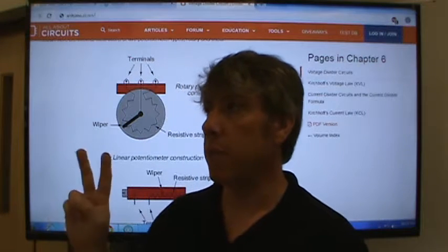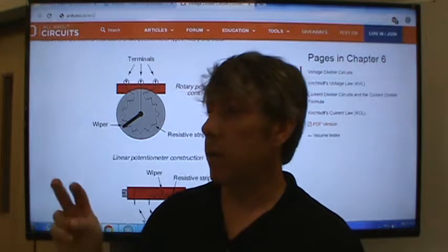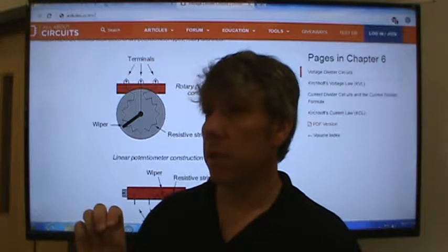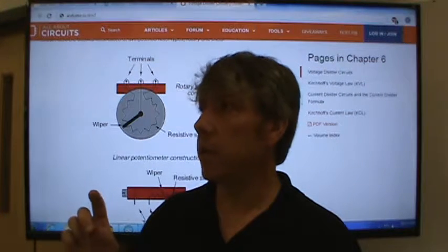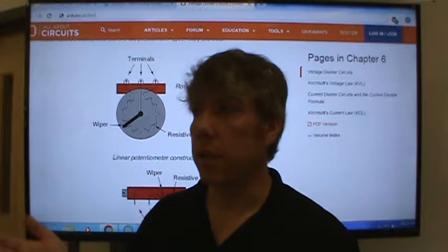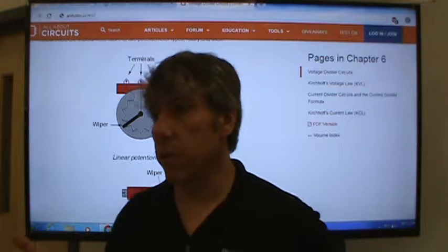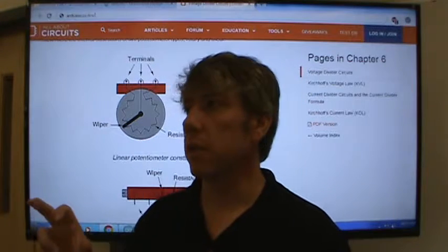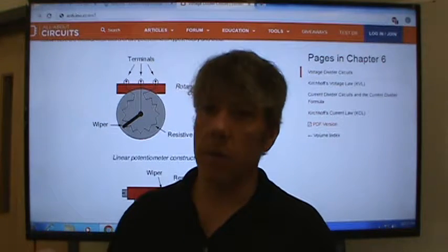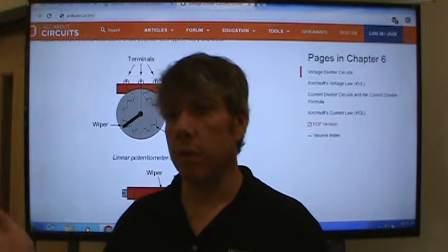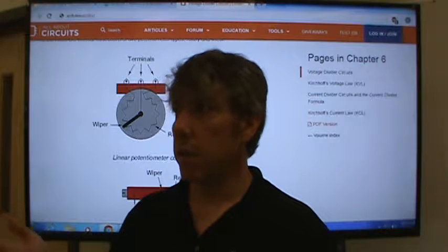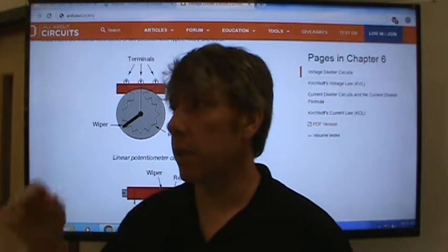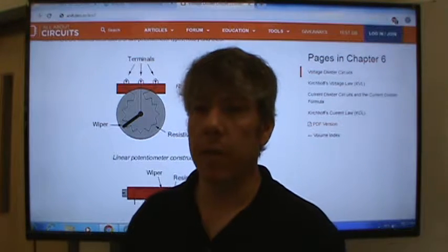I mean, if it's a 2-bit input, then we can only have 4 different levels of voltage, right? 00, 01, 10, and 11. So that's not very good resolution. That would be less than a volt of resolution on a 5-volt scale, because you need to represent 0 volts with 00 and 5 volts with 11. So the other voltages would be a quarter of the way along that scale. So anyway,